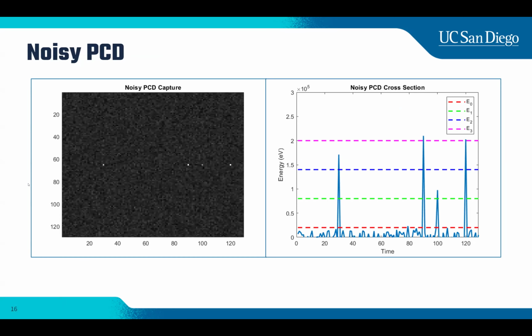So after adding some randomized noise, we can see on the right that while there is noise, you can still very much differentiate each and every pulse, every incident of an X-ray photon over a time scale. This would typically be in nanoseconds, maybe even smaller. And usually, if you set a threshold, everything under it is just discarded for energy acquisition, so that when it is processed through some program, you get a cleaner image with high contrast to noise and high signal to noise ratio, as opposed to an energy integrating detector.